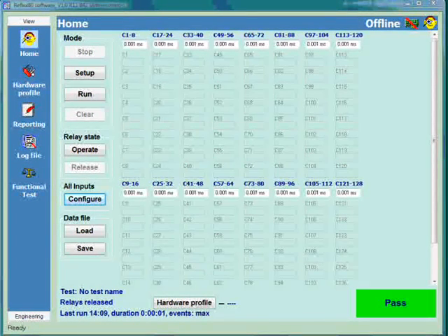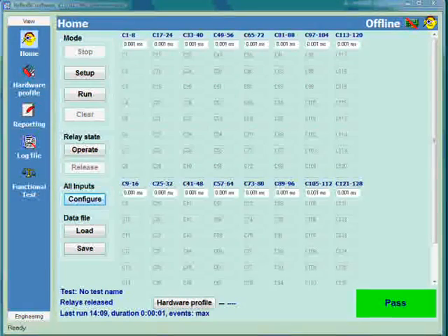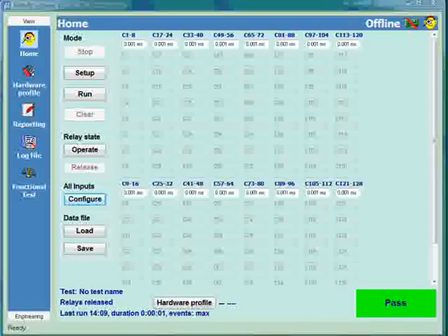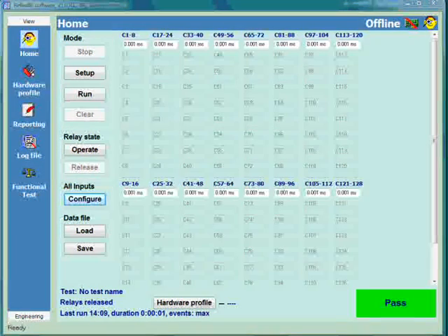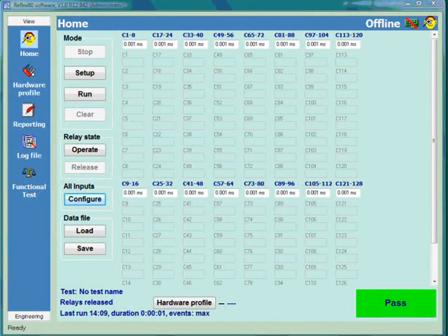It's predominantly used for applying chatter tests to military and other relay test specifications, and applied relay testing offer it as a modular system that can provide a number of groups of uncommitted individual inputs. These inputs are normally mapped one-to-one onto individual relay contacts, such that the contact names can be made visible on an operator screen. This page shows you the operator screen before any test data has been loaded.